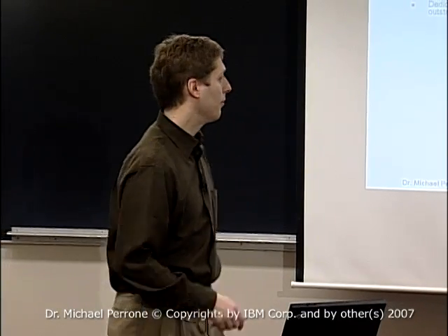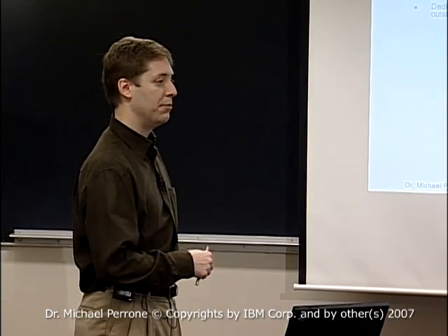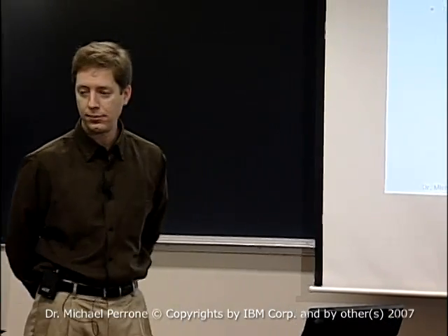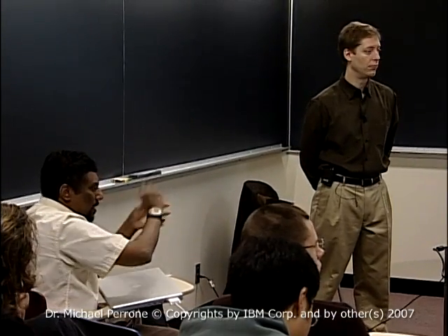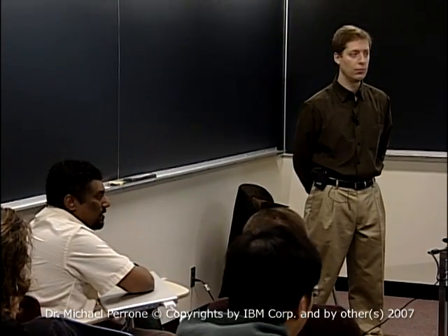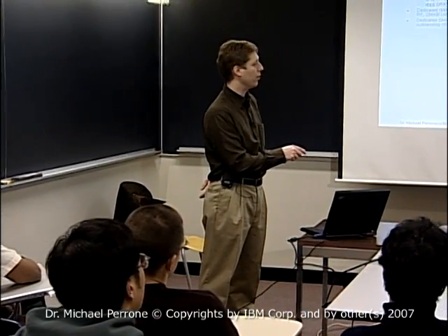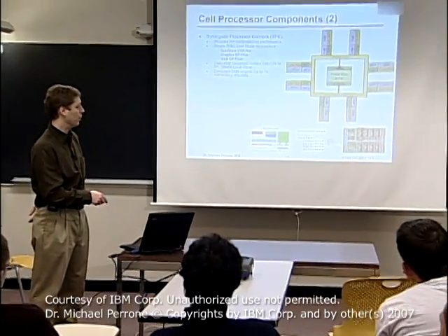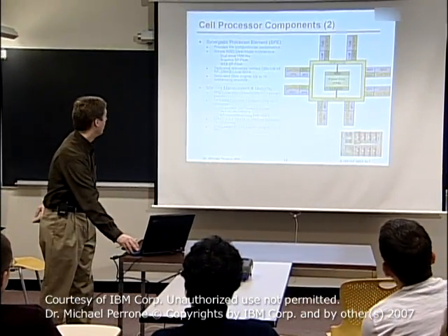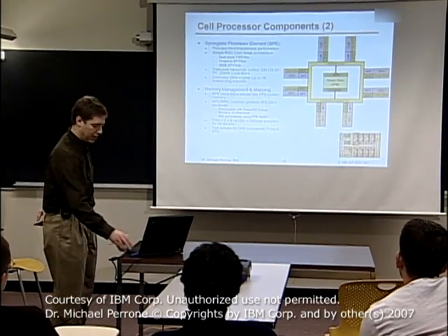The DMA goes onto the single bus, and that goes to a connection to the outside memory. Right. But you can address data in other SPUs too. You don't have to always go to outside memory. Right. You can do SPU to SPU communication, basically. So I can do a DMA that transfers memory from this local store to this one, if I wanted to, and vice versa. And I can pull stuff in through the... Yeah, I mentioned this stuff. Okay.